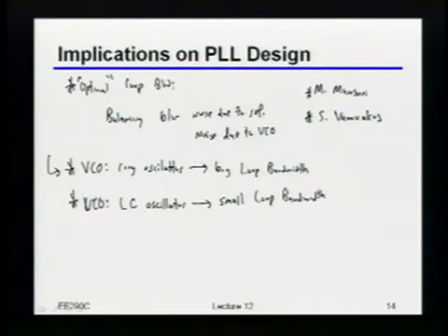And by the way, a lot of times people will actually build what's called a cleanup PLL. They will really put on their own chip a really, really good clean LC oscillator just to get a very high frequency reference. Okay, and then they'll use that to distribute the clock, or use that as a reference into a ring oscillator based thing or something like that.